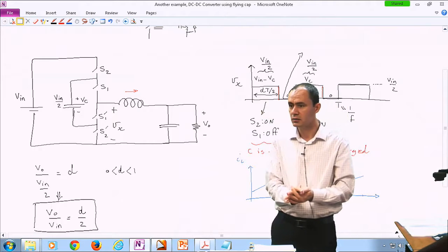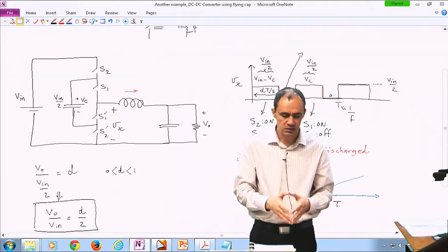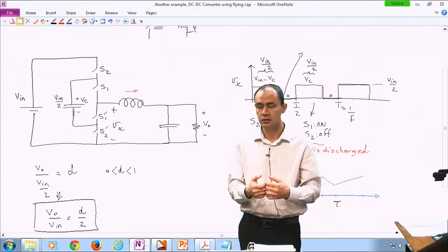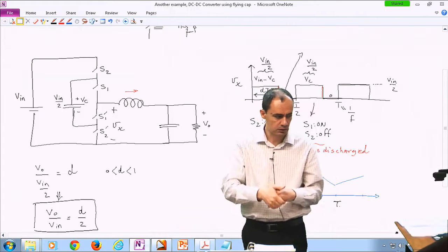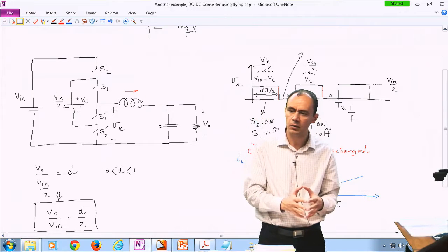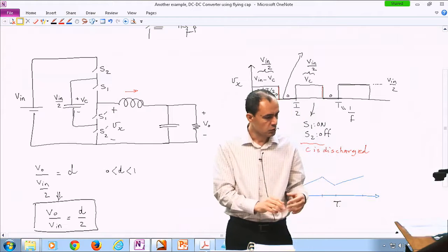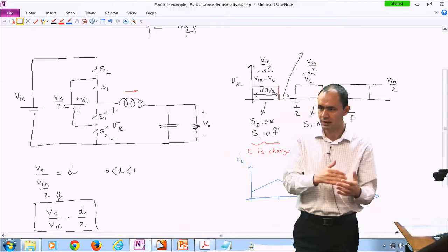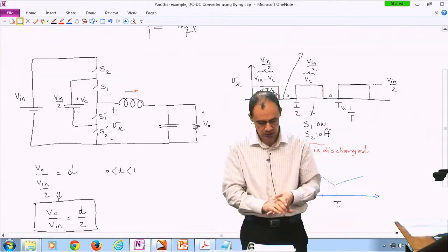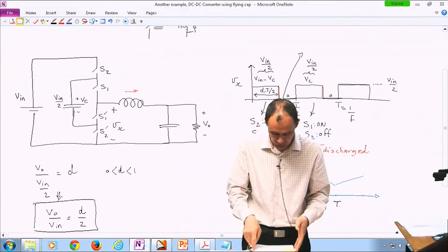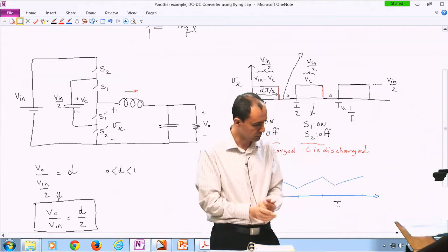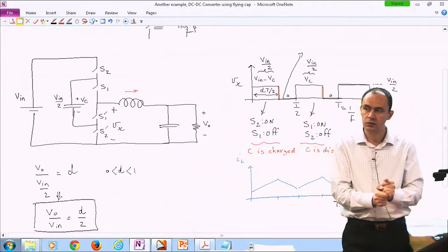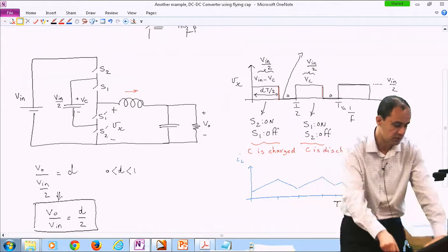So that's an advantage. Technically, when it comes to designing this system, remember the higher the effective switching frequency is, the smaller the required inductor is. So higher frequency, smaller inductor. It also has an inherent frequency doubling effect. There are a few papers out there focusing on this topology and using it as a DC to DC converter. If you are interested, I can find them for you, but it's not really that hard. They are on IEEE Xplore. So that's another advantage, that the effective switching frequency is twice as much as the real switching frequency.